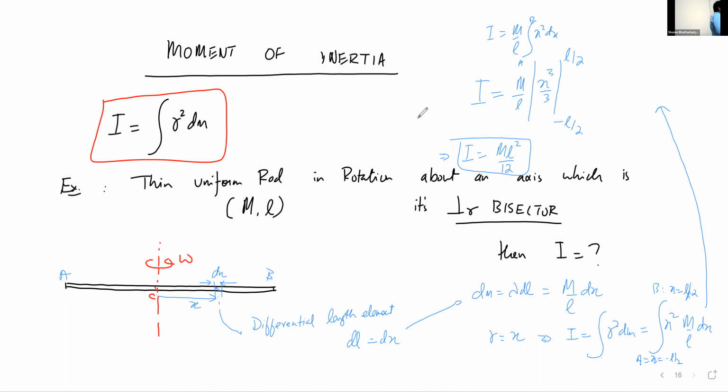So that's I omega. Or if we are thinking in terms of work energy, how much kinetic energy you have to absorb to bring it to rest, so that is half I omega squared. So what does that depend on? It depends on two things. It depends on the speed of rotation, which is omega, and it depends on another property, which is the internal property of the body. It's a physical property of the body. And that is basically what? The distribution of mass with respect to its axis, which is moment of inertia. That is defined by this integration r squared.